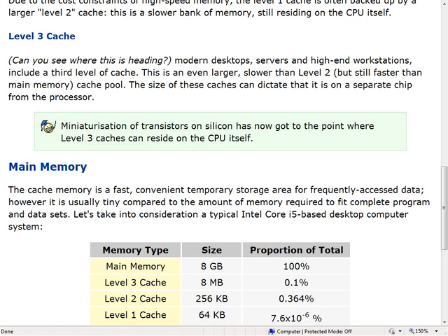So you'll have processors that have the same clock speed, same features in terms of all that fancy stuff we were talking about last week, but the level of cache is different. When they build these in the fabrication areas, they'll try and build the best one with the full set of cache. But if they build one and the processor works all right, but in one part of the cache the memory's not really working right, they'll disable half the cache, because it wasn't working reliably, but the other half still works. Then they'll sell that as a lower end version of the chip, and this is what's called chip binning.